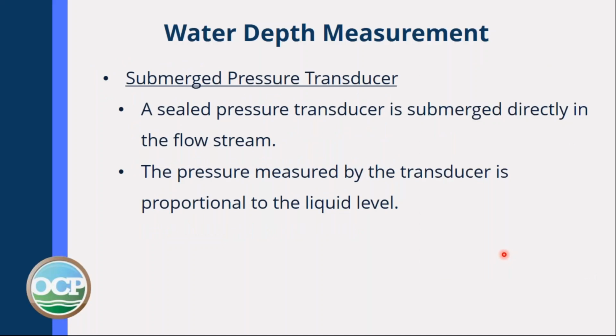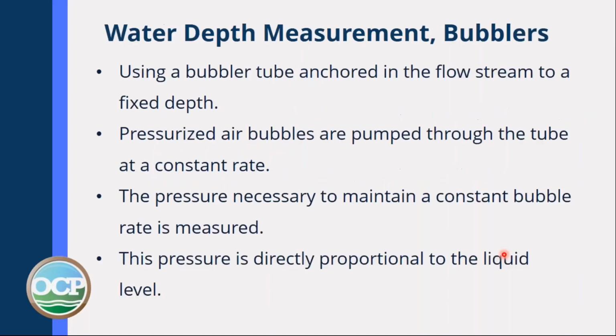We can have submerged pressure transducers. And again, if that's at the very bottom of the channel, then the depth of the water will change the pressure, and you can determine the depth of water from that change in pressure.